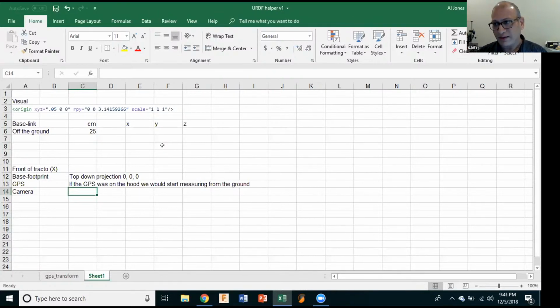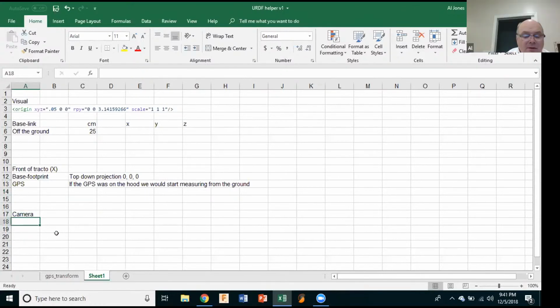And that would be from base link, I would say, let's go 1 meter in X direction. And then Y 0, because you're mounting right at the center, let's say, for example. And your Z is almost the same height as the base link height, which is like 25 centimeters. So now you got all these 4 points, right? Are you with me so far? No, I'm a little lost.